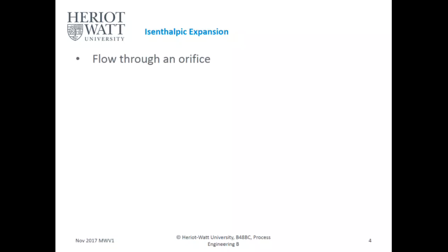So what's isenthalpic expansion? When you put a gas through an orifice and it expands, basically the enthalpy remains constant. So that's isenthalpic expansion. Now, that's not really what happens in the real world, but for the sake of this course, that's what we will be looking at. We'll look at real gases as well, but not in too much detail.